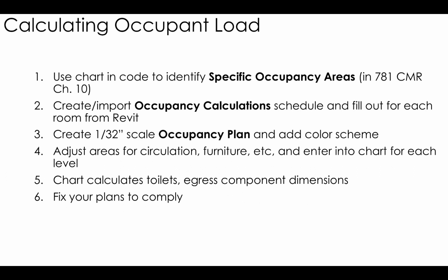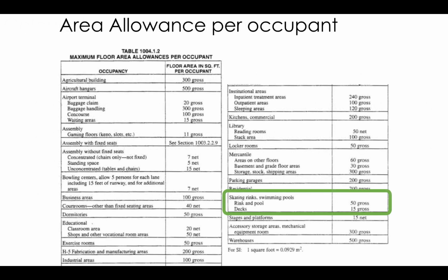So this is straight out of the building codes class. There's kind of a process here. Now, our project is pretty simple, and for this stage, we're just going to do a diagrammatic plan. It does not have to be a 1/32 of an inch scale. But we're going to be given the number of toilets, so you don't have to worry about that. But the big thing is calculating the number of people in there is an exercise you should always do for construction drawings.